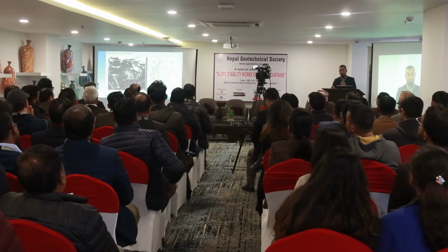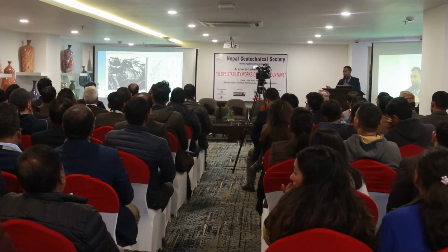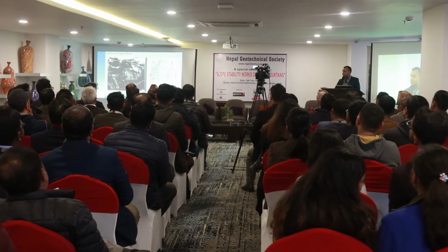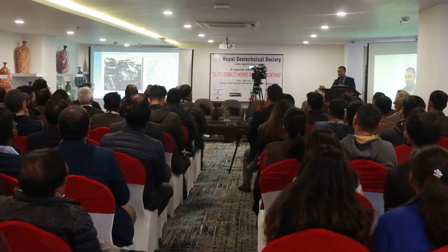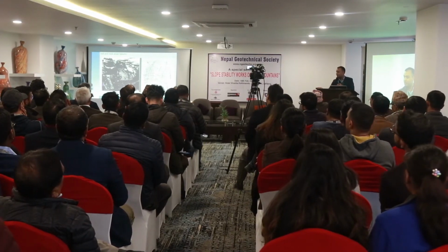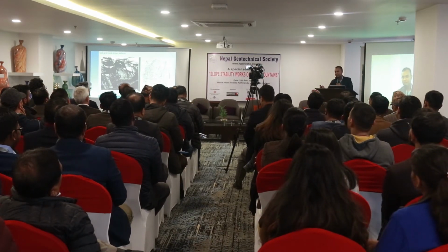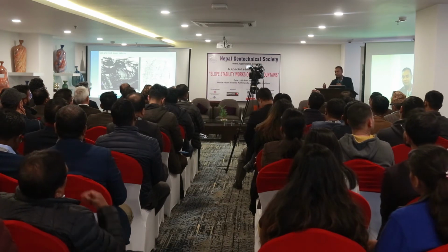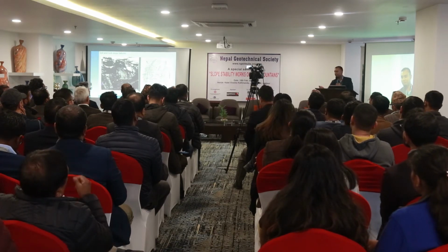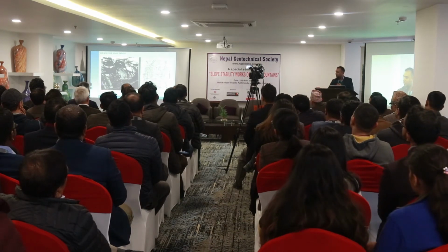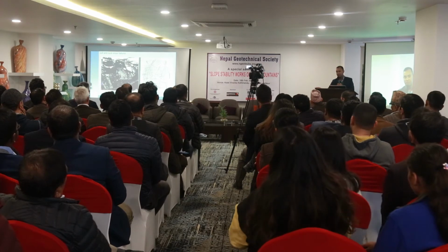Another one. Those are the natural slopes, and this one I don't have the picture. It was taken in 1978. It's also for the same dam, Revelstoke Dam, when they were excavating a 14-meter diameter diversion tunnel, and they had a failure just upstream of the diversion tunnel. And you can see, I think, just here, the heave of around 14 million cubic meters of rock, all at once. And I think there were very few fatalities.